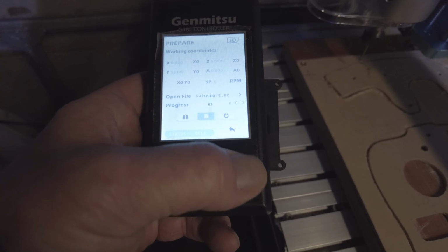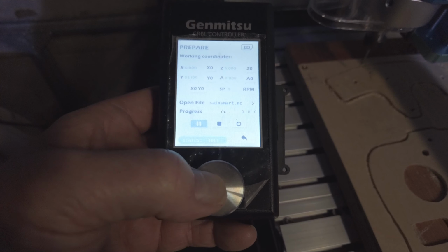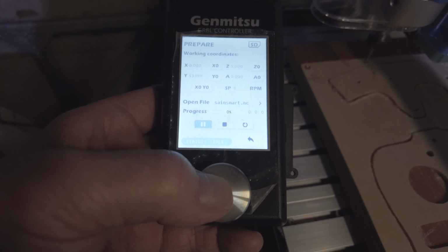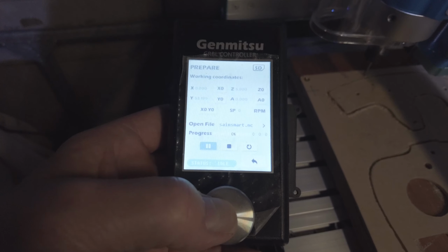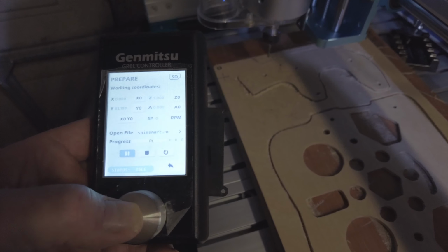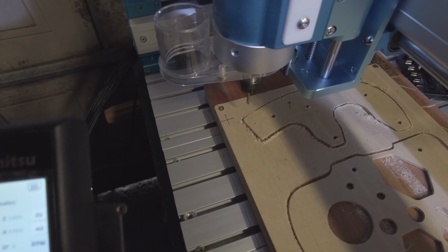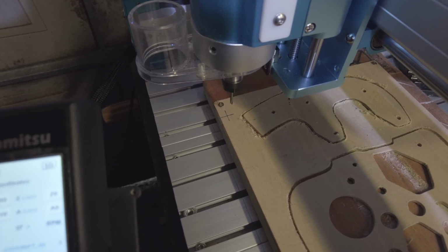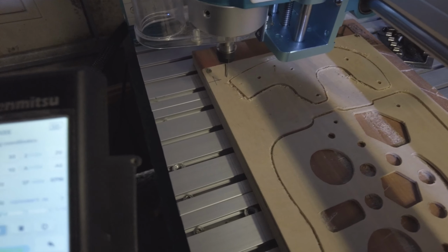Okay, so we go down and we'd install as new Sainsmart, whatever your toolpath program is, install that, and then you go back down to here. Okay, and then what you would do then is, remember those coordinates there originally were set at 0, 0, so what we'd do is run the program. Watch what the machine's doing. Going back to 0, 0.